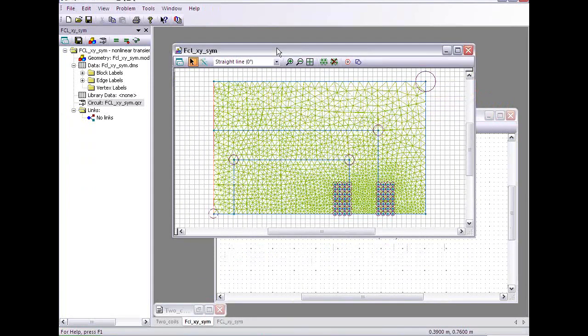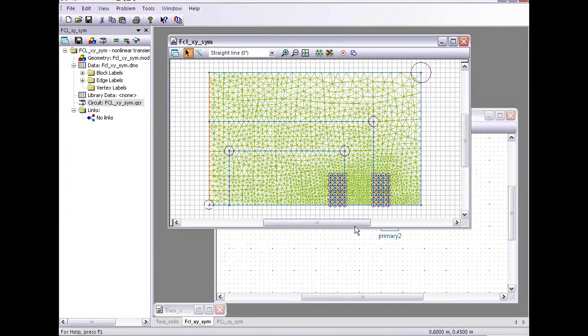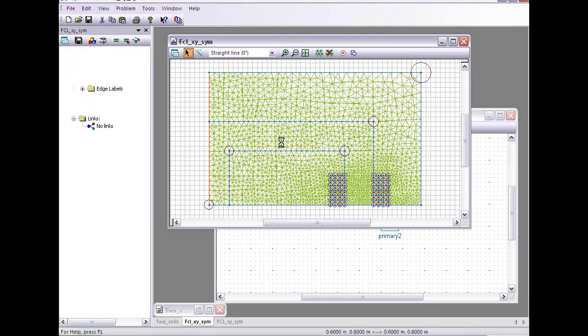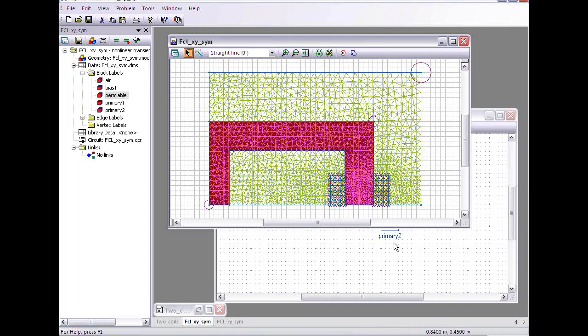Now, once again, these particular designs involve superconductors, but we're not driving the superconductor normal as we did in the case of the inductive fault current limiters. The superconductor is just used to maintain the coil in saturation, the permeable region in saturation. As well, the primary coil won't necessarily desaturate the entire circuit. We would just be looking at desaturating a smaller region of the circuit here.